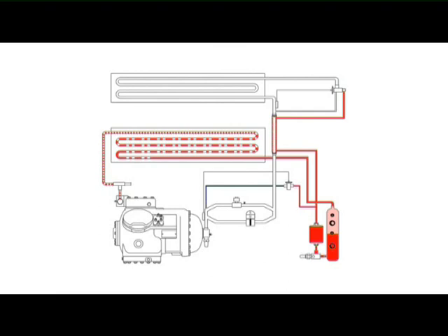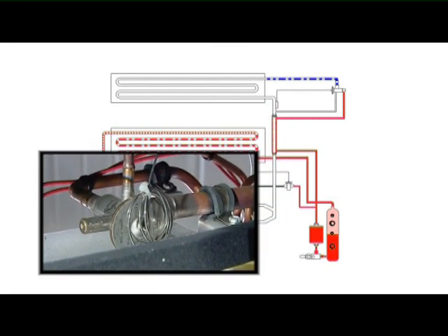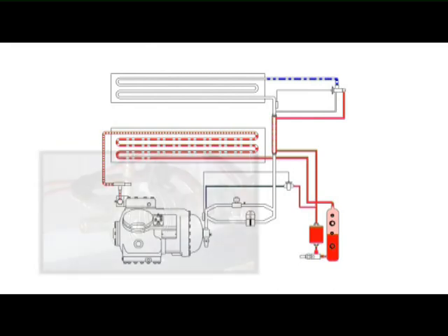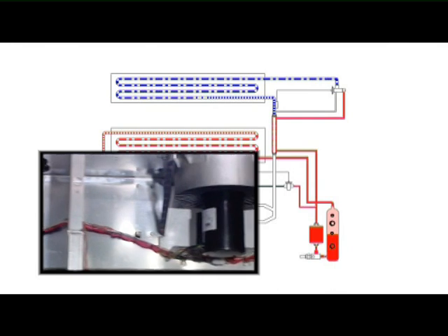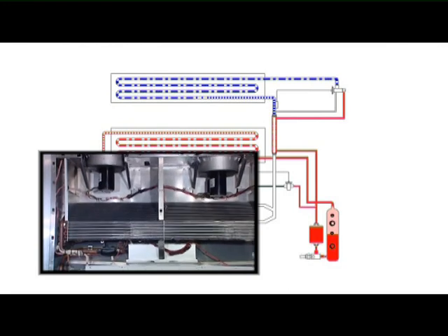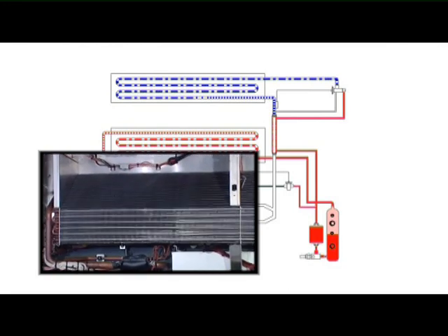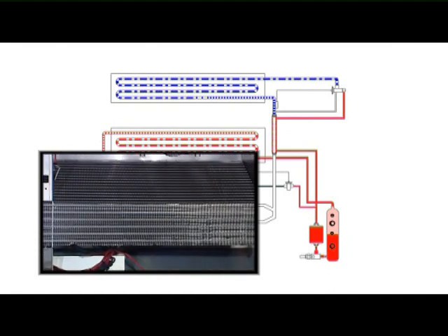The refrigerant arrives at the thermostatic expansion valve TXV, which measures the amount of refrigerant entering the evaporator coil. As the refrigerant passes through the TXV valve, there is a pressure drop from the high side to the low side of the system. The low pressure and low temperature saturated mixture from the TXV valve enters the evaporator coil. The air circulating over the cargo by the fan motors is also circulating through the evaporator coil fins. Heat from the cargo is transferred to the refrigerant inside the evaporator coil. Heat is absorbed, causing the refrigerant to boil into a vapor.